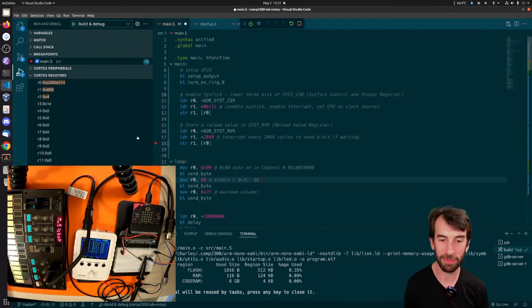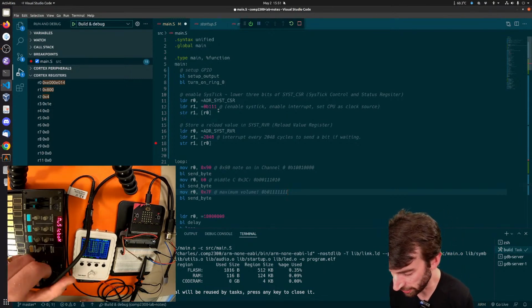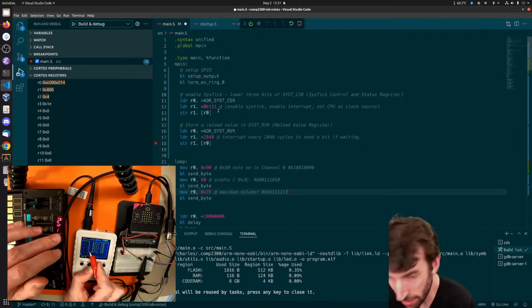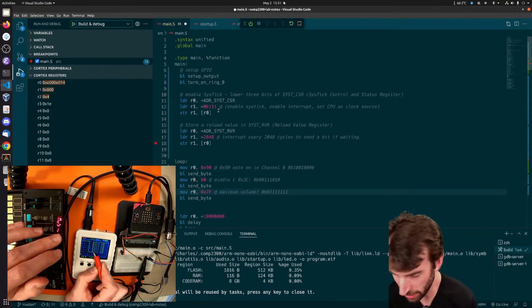That's 0B3, which is going to be 0011, and the C, that's 10, right? So it's going to be 1010. And then 7F is 0B01111111. So we can start to decode this message looking at the scope. There's our start bit. Then we've got 4 0s, then 1, 2 zeros, and then another 1, and a stop bit. Next note, start bit and stop bit.